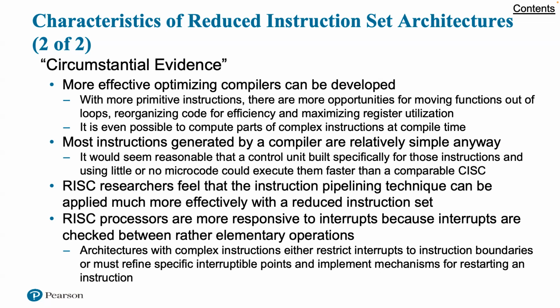A final and somewhat less significant point is that RISC processors are more responsive to interrupts because interrupts are checked between rather elementary operations. Architectures with complex instructions either restrict interrupts to instruction boundaries or must define specific interruptible points and implement mechanisms for restarting an instruction.